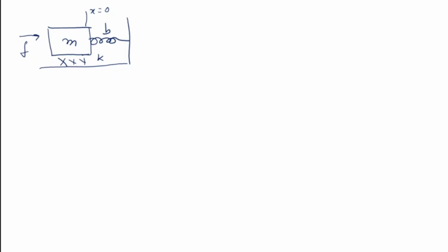But anyway, either of them, it is going to come back to somewhere near the origin. So basically it says that if I'm going to give it a slight disturbance and I'm going to leave it, so I take it to some distance x there, and then I leave it, depending on the values, it will come there and it will come here. So depending on the values of MBK, whether it is overdamped, underdamped, or critically damped, it will come back to where it started off. Now, will it come back exactly to the origin? Well, you need to think a little bit about that.